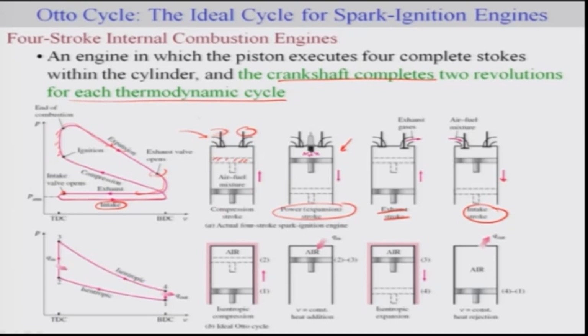Here the first step corresponding to this image is nothing but your compression stroke, followed by your expansion stroke, followed by your exhaust stroke, followed by your intake stroke. Now this becomes a complete cycle. So you have compression stroke, expansion stroke, exhaust stroke, and intake stroke. It is very clear that this is not a closed system or not a closed thermodynamic cycle. This is open because your air-fuel mixture is renewed again.